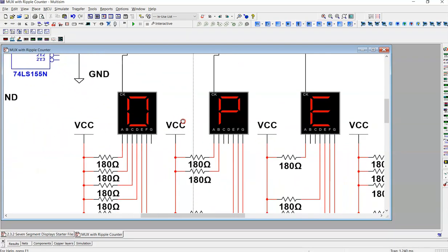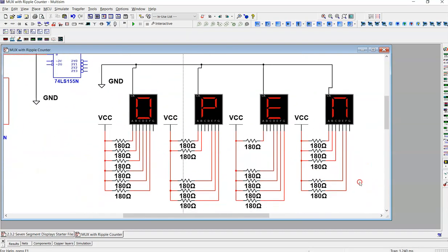So kind of walking this out, when you're looking at activity 233, start with the idea of just building a small section of this and testing it. So first, I'd bring in your power, your resistors, and get your 7-segment displays to correctly display the word that you want to display. Here in this example, they've got the word open, and that's already shown for you in the procedures.